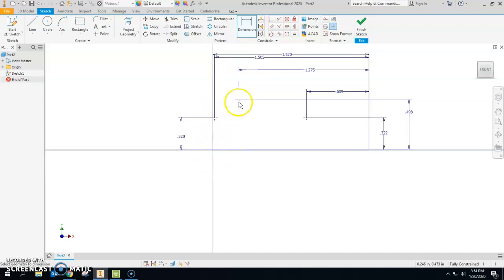I'm going to use an arc from here to here, and then the spline tool for the rest. So let's grab my arc tool, and I'm just going to put this in first and make sure it arcs in the right direction, and I'll come back and dimension it. Get that close. And then now before I move on to the spline, I'll do this. So the radius that we get there is 3.